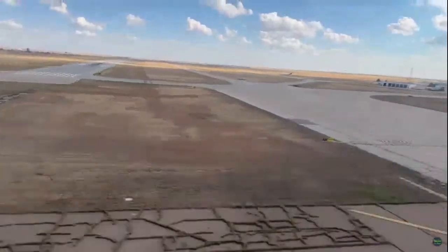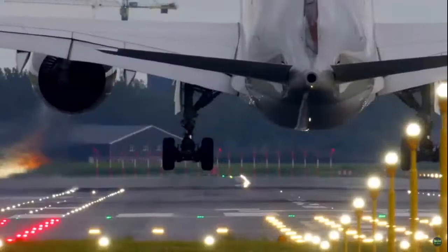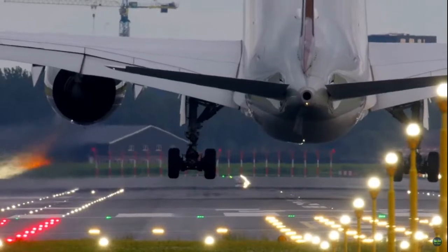This flight, Jeju Air 2216, came in clean, meaning there were no flaps deployed either. Again, that could be a telltale sign of hydraulic issues. Or just flaps not being deployed. So normally when you land, you want to have the flaps down to 30 or 40 degrees to minimize the needed airspeed coming in.